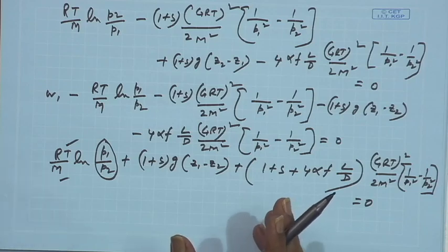So, here, normally as an engineer you would like to know that you want to send this much material, maybe powder or some granular material, from one place to the other. So, what should be the pressure drop? That is one fundamental thing which you want to know, because that will dictate major investment from your side in terms of pumps and others, motors; all these will be dictated by that. So, there you would like to know if the inlet pressure is so much, what is the exit pressure, or vice versa. If the outlet pressure is so much, then what was the original inlet pressure.